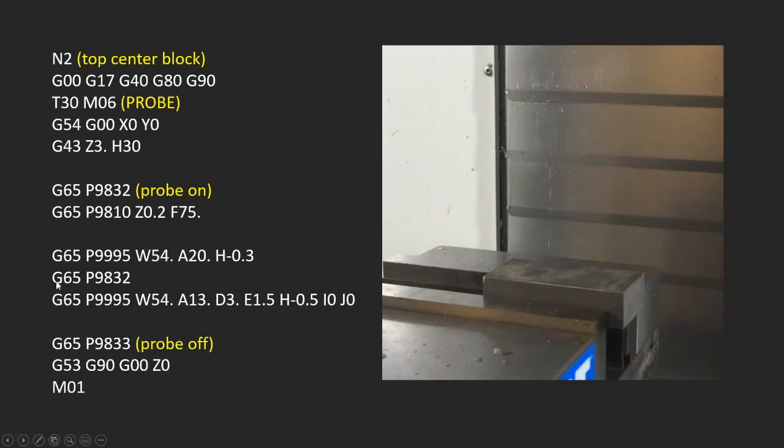When we're done running that, we have to turn the probe back on. You can see that that's the same code up here. And then we'll do the center of a block, which is what this code does here. And because this came from conversational programming, I'm not really worried about exactly what it all means because I'm just getting it and plugging it in and using it. The difference is that when I do it this way, every time I get done with a 9995 line, I have to turn the probe back on to do another one. So that's an important part of that, which we talked about in the second webinar.